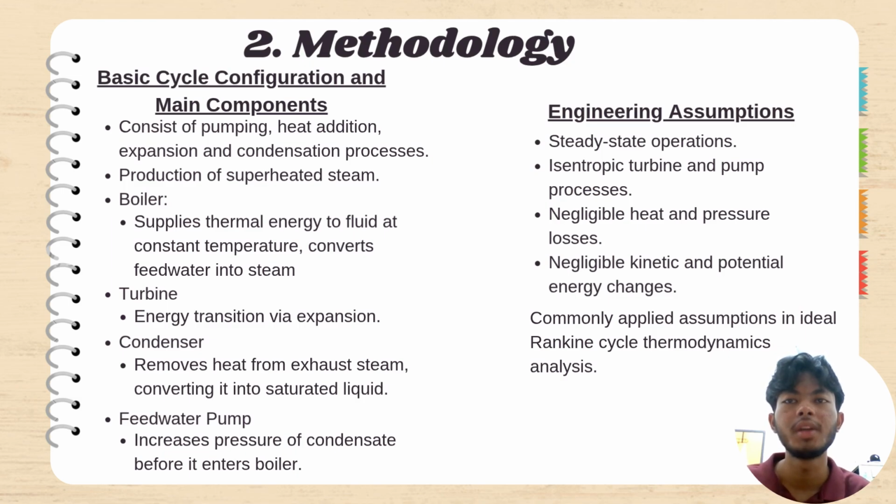can continue. In this simulation, we used ideal Rankine cycle assumptions. The system is considered to operate at steady state, while the pump and turbine are assumed to be isentropic. We also neglect heat losses, pressure losses, and changes in kinetic and potential energy to simplify the thermodynamic analysis.